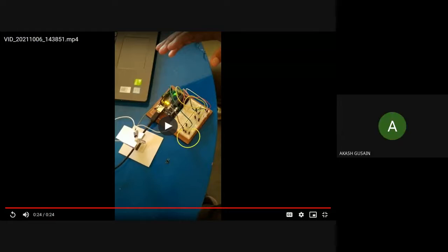This question has been asked, but what would you do if you are getting values between 100 and 160? Because the accuracy will be too low for your system, right? We can map that, I guess, using the map function. How does the map function work? We first give the value, then the initial range that we are getting, then the range we want to map it into.